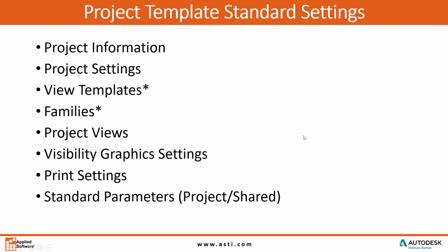So some standard information or settings that you're going to want to configure in a template is your basic project information, project settings. Now, view templates and families, there's asterisks here because view templates are going to be really critical to a project, because when you set up a project, you have to go through a whole bunch of graphic settings to make it look good so that you can distribute to the team the proper floor plans, ceiling plans, elevations, and so on, right? So you use view templates for that.